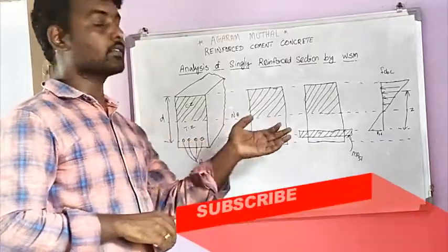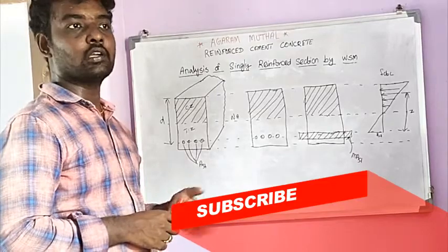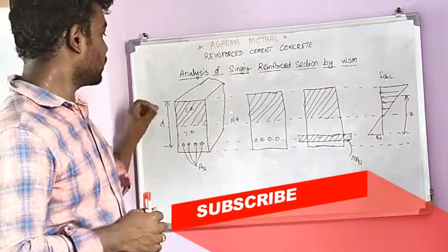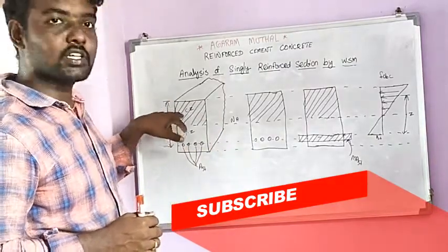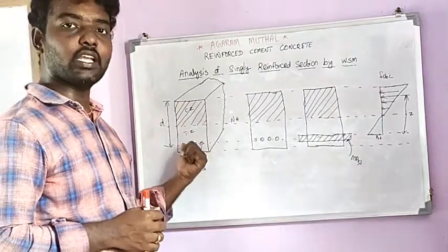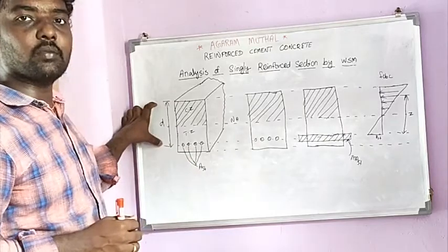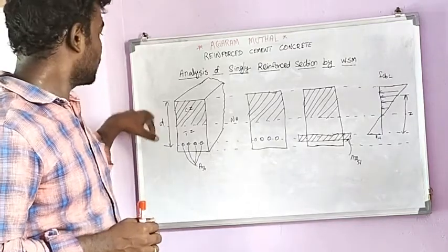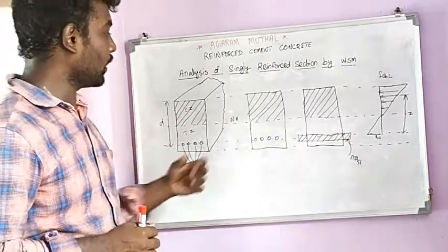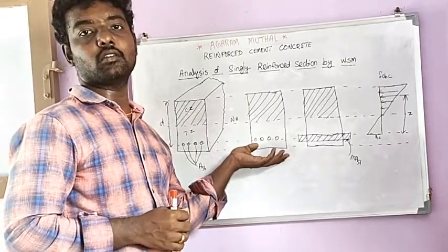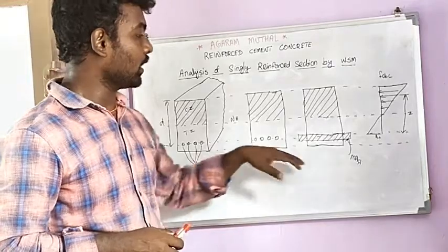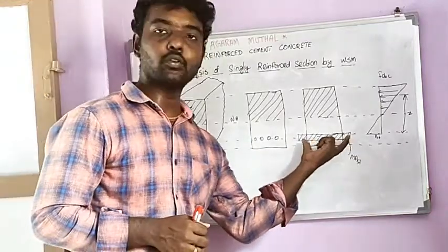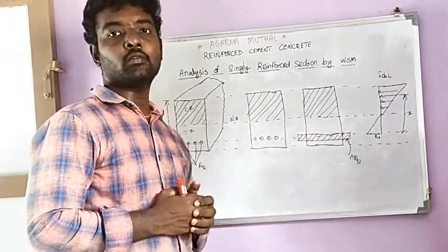Some stress strain pictorial drawing, which shows the relationship of the singly reinforced sections. So here is the beam, which has both compression zone and tensile zone, and the reinforcement is provided only at the tensile zone. The depth is nothing but the extreme top end to the center of the bottom or tension zone reinforcement. This is called the effective depth, and this is the stress drawing of singly reinforced sections, and this is a transformed section which we talked about in the assumption part. So we have to consider some transformed portions for better bonding purpose.